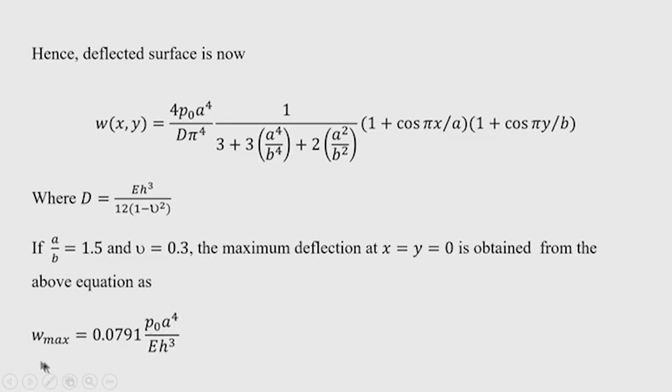cause any difficulty for practical applications, but we have to see whether the second and third derivatives, which are used to find the bending moment as well as the shear force, retain accuracy or not. That comparison should be made, and it is obvious that with the use of only a single term in the series, the accuracy in the bending moment and shear force will be lost. So, if you want accuracy of these two parameters, then you have to increase the number of terms in the series.